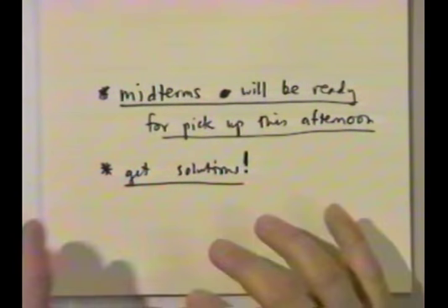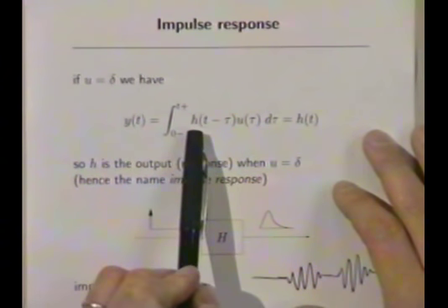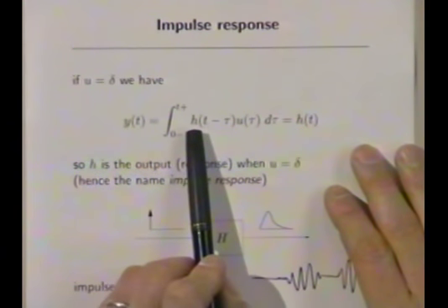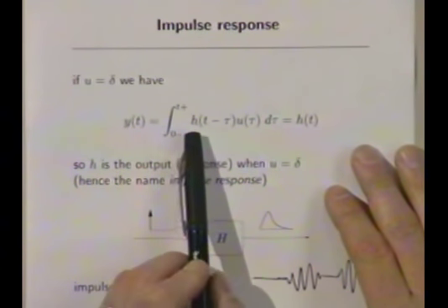I guess last time we were looking at transfer functions and convolution systems, and we looked at impulse response and step response, and these are both quite important ideas. Impulse response is, of course, there's many ways to think of it. First of all, when you look at a convolution system, it's simply this thing here. It's the convolution kernel, or there's various names for it. I guess in engineering, it's almost universally called just the impulse response. It's called the impulse response for the following obvious reason. If you put an impulse into the system, this is what comes out.